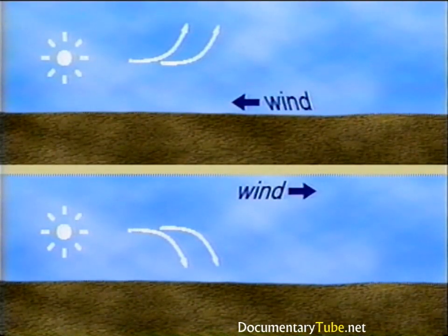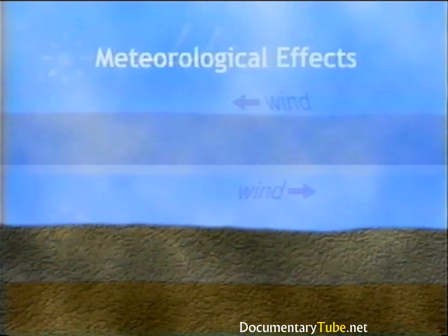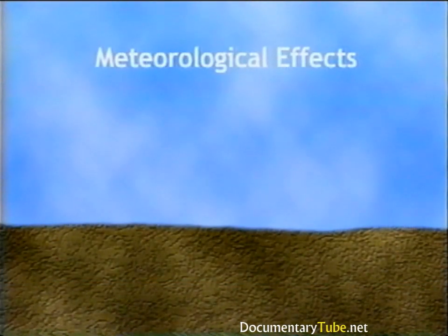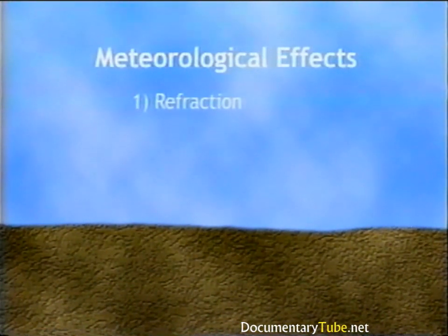And when sound is propagating downwind, the ray paths curve downward as with a temperature inversion, increasing the received noise level. The importance of meteorological effects is that sound may reach the receiver with greater intensity if it is refracted downward toward the earth, and with less intensity if the sound is refracted upward away from the earth than in cases where meteorological effects are negligible.